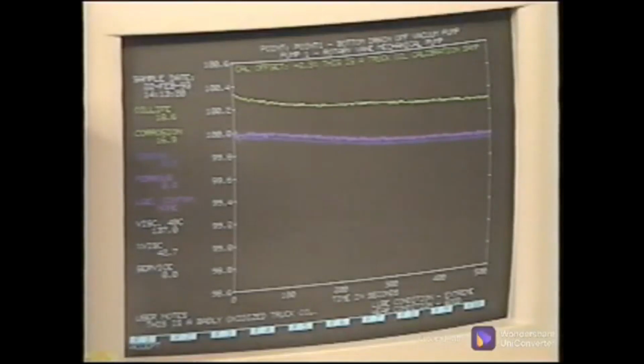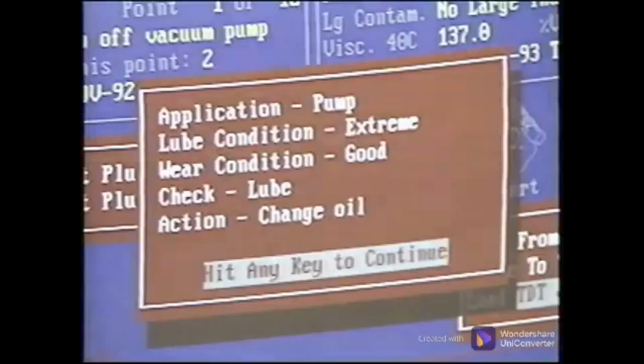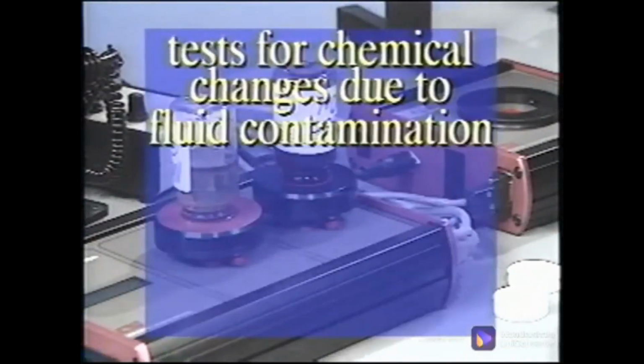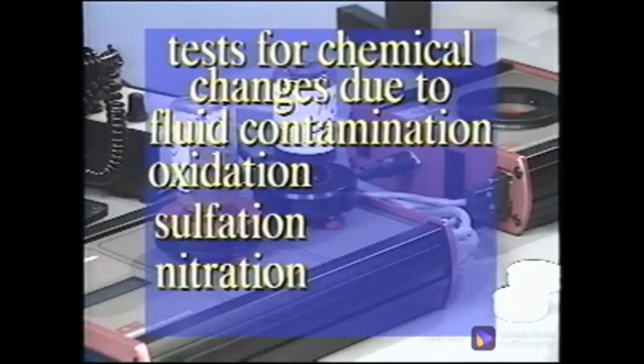The comparison of the two can be displayed graphically and are noted in the indices with recommendations reported in the automated diagnostic function. This analyzer provides a good indicator of any chemical changes that result from soluble fluid contamination, increased acidity, the occurrence of oxidation, sulfation, and nitration, as well as the presence of soot. The on-site tests for lube quality provide instant results assuring you of the vital functions of the lubricant.